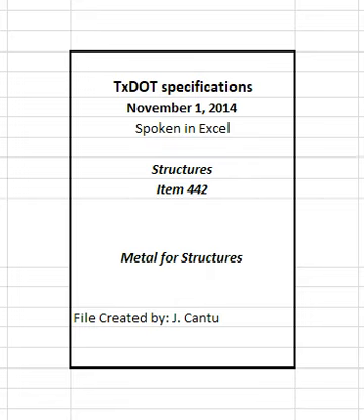2.1.3.2 Shear connectors and anchors. Provide cold drawn bars for stud shear connectors, slab anchors, and anchors on armor and finger joints that meet the requirements of ASTM A108, grade 1010, 1015, 1018, or 1020, either semi-killed or killed, and have the tensile properties given in Table 2 after drawing or finishing. Determine tensile properties in accordance with ASTM A370.